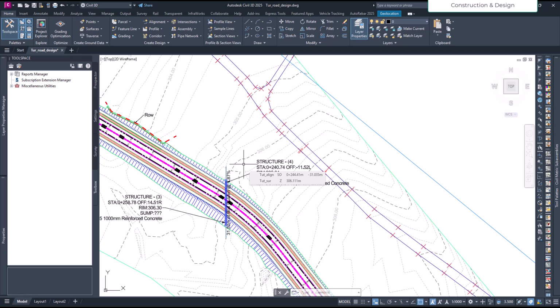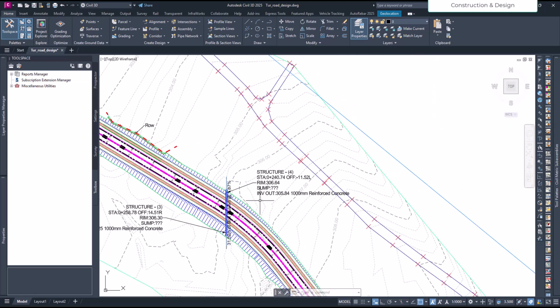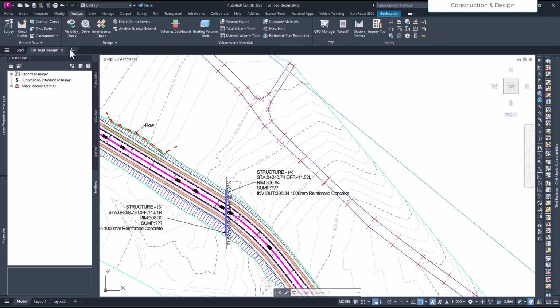But in this video, we'll see just the calculation. We have already seen inserting the culvert and creating the cross section. So let's go ahead and see where the tool is located. In the Analyze tab, at the top, on the second page, you have the Design option. As you click over that, you have four options. Today we are going to talk about Launch Express. Hydraflow Express is the tool that we're going to use for this video. So let's click on it.